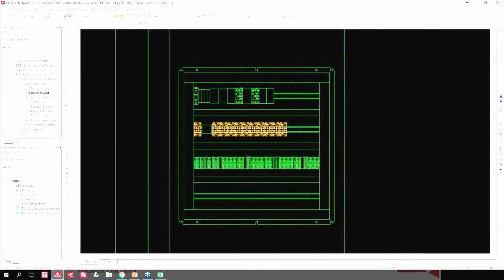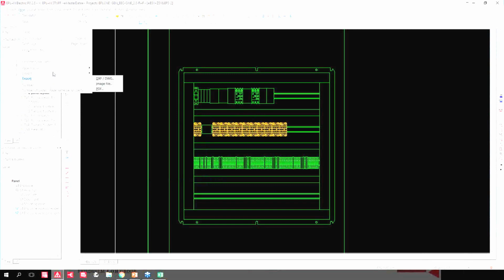We can go into the PDF and modify it, and we can import that information back. Here I have the capability of importing the PDF comments that were made inside the PDF environment. So if I need to redline, I don't have to have EPLAN open. I can just use the regular Adobe Reader, make some markups, and then import that information into my project.